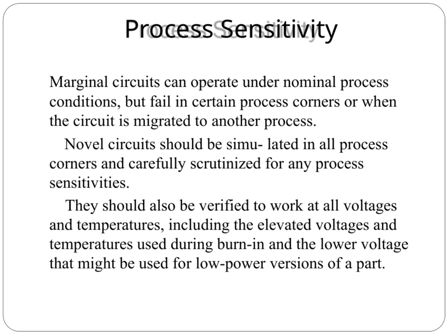We must simulate and analyze them under a wide range of scenarios. Additionally, we need to ensure these circuits function properly across all voltages and temperatures. This includes the higher voltages and temperatures used during burn-in testing, as well as the lower voltages that might be implemented for low-power versions. This comprehensive verification helps prevent failures and ensures robust circuit performance in real-world applications.